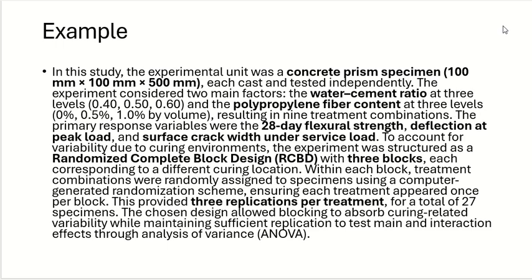It may not show in your experimental design, but it will definitely affect your values, and then you cannot justify why you did 3 different water cement ratios and it's not showing any effect. Why is that?